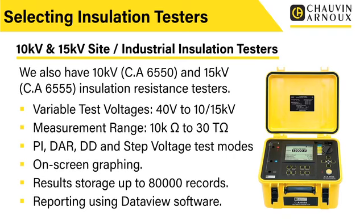And these have got all the features that I've just talked about with the 5 kV products, but they also add a few extras on as well. And obviously the increased test voltage is part of that. So we have variable test voltage, in this case from 40 volts up to 10 or 15 kV. We've got a measurement range from 10 kilo ohms all the way up to, in this case, 30 tera ohms. So we've got the ability to do all the usual stuff, the PI, DAR, DD and step voltage test methods.